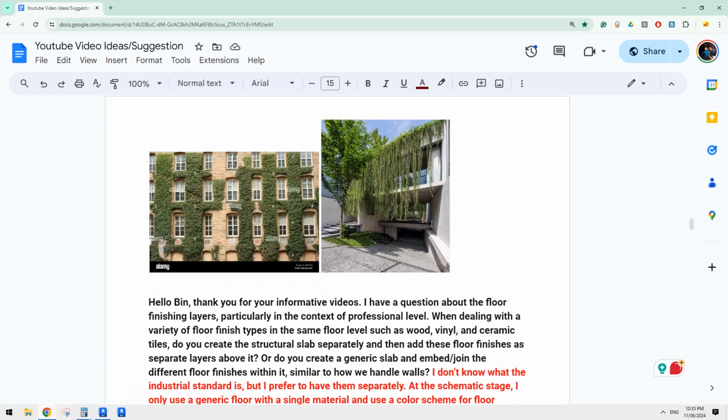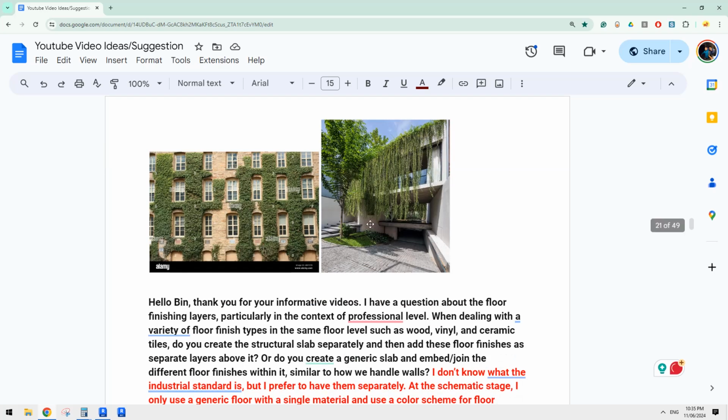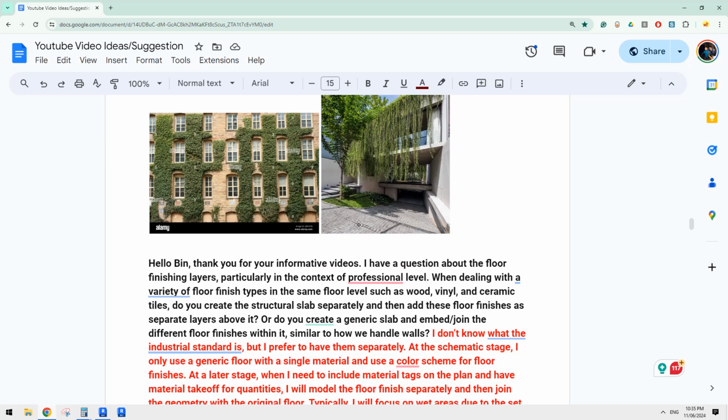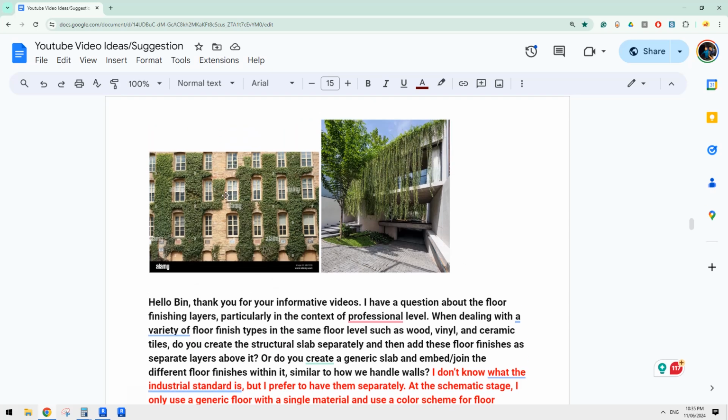Let's go to the next one. Okay, so these, don't model them. Usually what I do, if I want to model exactly something like this, I will just model in place with a material, so it looks like this. Just create using pick the wall, create a model in place extrusion. I'll create something like this shape.